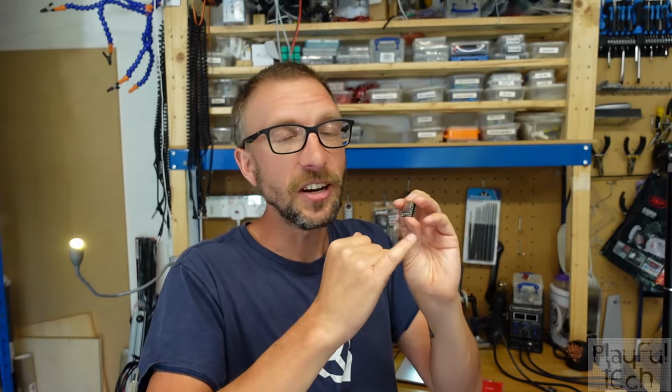Or if you want to use it as a soundboard, you can connect different resistor values to 2 of these pins to trigger up to 14 different tracks directly. Or you can create a serial connection to a microprocessor like an Arduino and send serial commands that allow you complete programmatic control over all of its features through code.